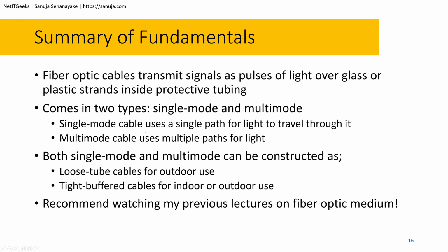And I told you that the single mode uses a single path for light to travel through it, and the multi-mode cable uses multiple paths for light to travel through it. Actually, I haven't introduced that concept in depth in the previous slide, but that's basically the difference in terms of how the light is transmitted. Both single mode and multi-mode can be constructed as loose tube cables for outdoor use or tight buffered cables for indoor or outdoor use.